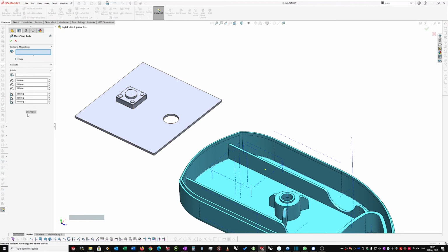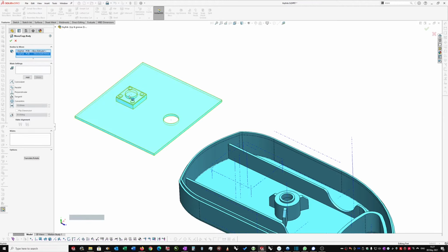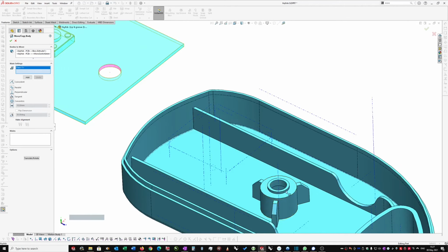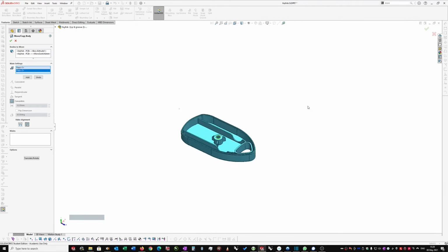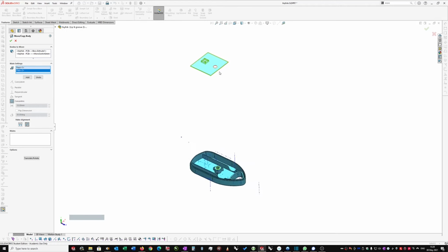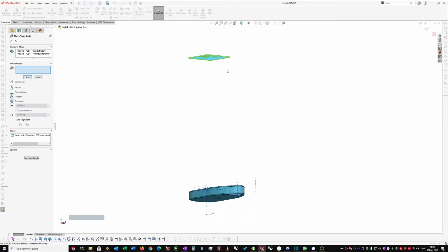So I'm going to click on this command again and just click right, and this time I want it to mate. So I'm going to click off constraints. I'm going to select my two bodies, 1, 2, make sure everything's selected. The mate settings, I'm first going to select this hole, and I want to mate to this pin, and you see it's immediately done concentric. It's gone off screen because it's up at the top here. So if I'm happy with that, I could click OK, but you can instead stay in the command and just say add, and so now you can add another mate.